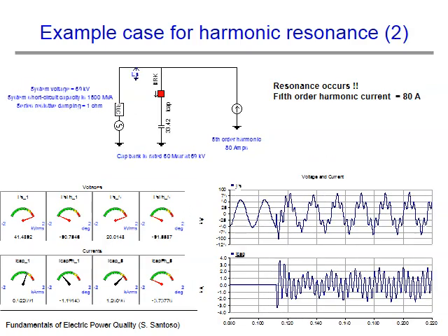Now, the energizing operation is repeated, but with the presence of 80 amps of harmonic current oscillating at the 5th harmonic frequency. With this current present, the transient, instead of being damped out, evolves into a persistent resonant response, resulting in highly distorted voltage and current at the capacitor bank.